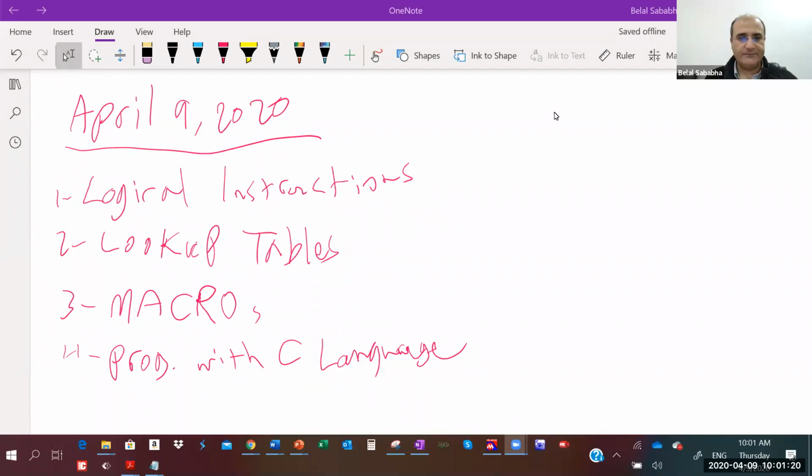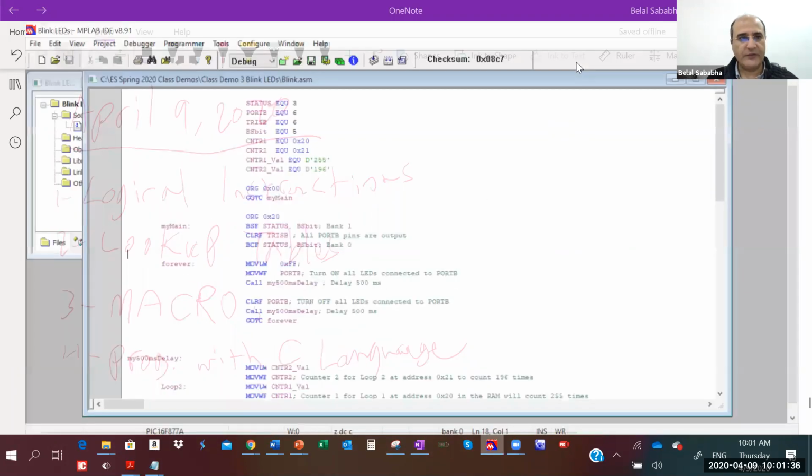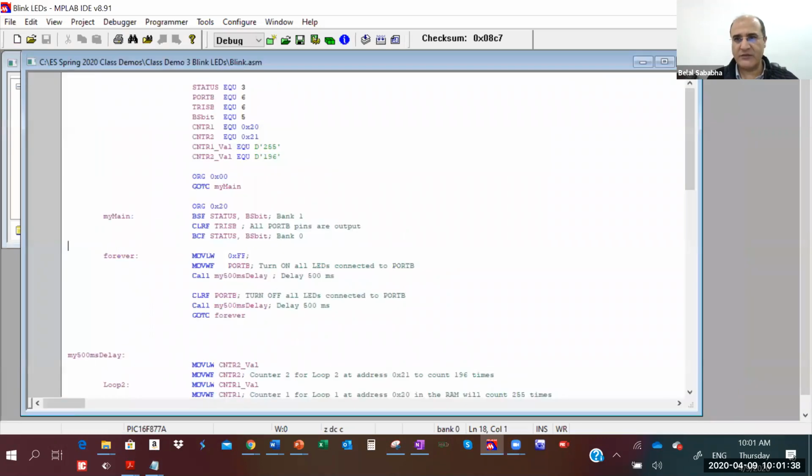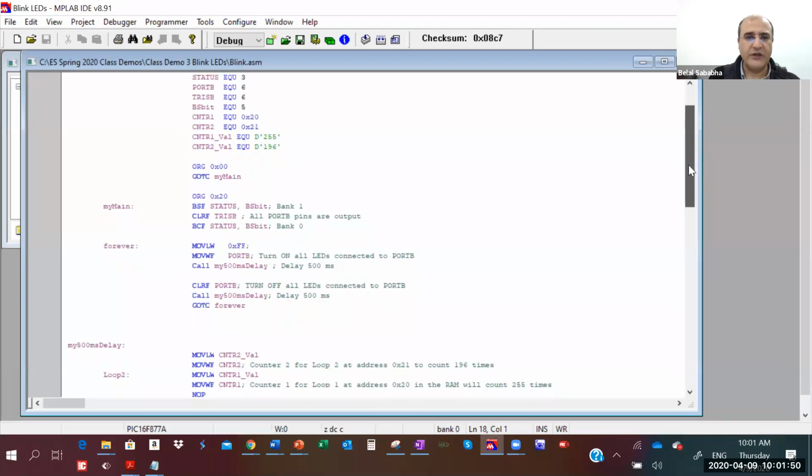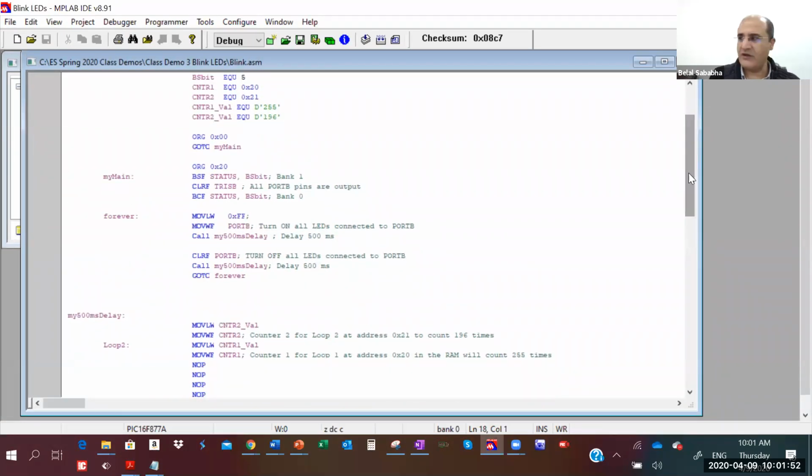Good morning again. In today's class, we're going to cover 4 topics: logical instructions, lookup tables, macros, and we start programming with C. To remind you what we did last time, we wrote a program in assembly. It's going to be probably our last assembly program we write, then we're moving to C. The program was about blinking LEDs connected to port B, on for half a second, off for half a second.